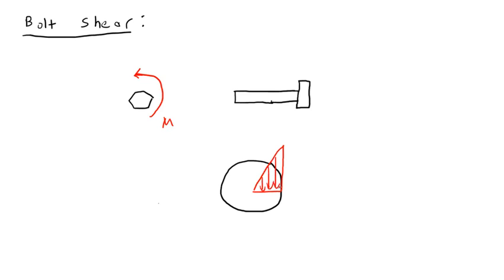So you have a very large amount of stress in the material on the surface, because the fibers of the bolt are in shear, and while they are in shear, that is producing an internal moment inside the bolt. And this internal moment must be able to resist the moment that you're applying. And this would be like an elastic condition.